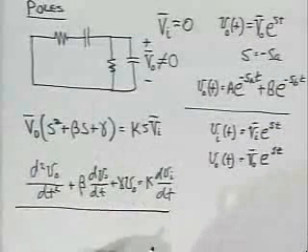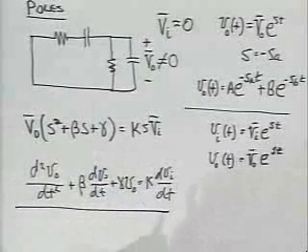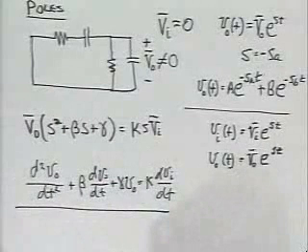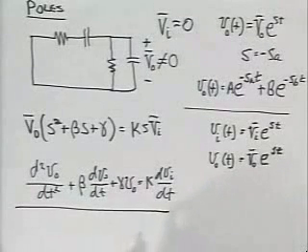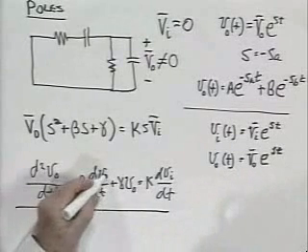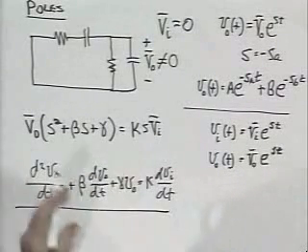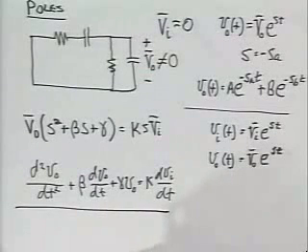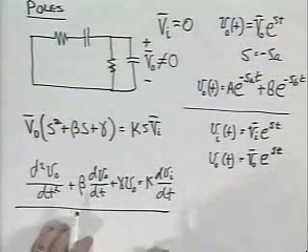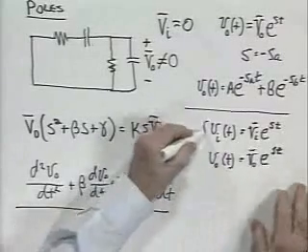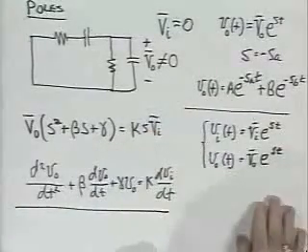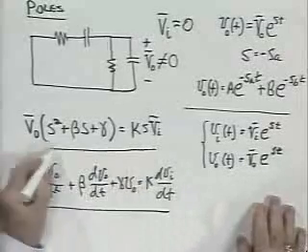The advantage of doing it this way is that instead of solving simultaneously two differential equations in the variables V sub O and V sub m, and then eliminating V sub m, instead of doing that solution in the time domain, if you will, we do the algebra here in the frequency domain, and then recognize that the differential equation must be this, because if I substitute in these variables and divide out the e to the st, that's what I'm left with.